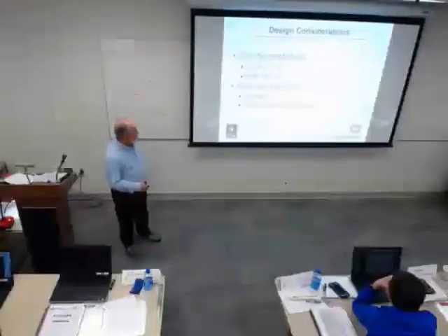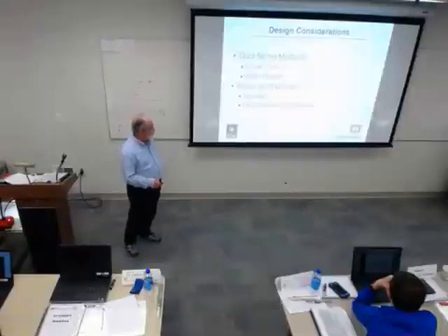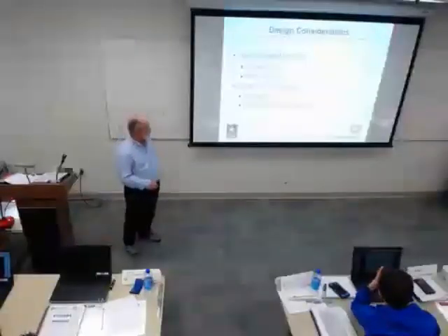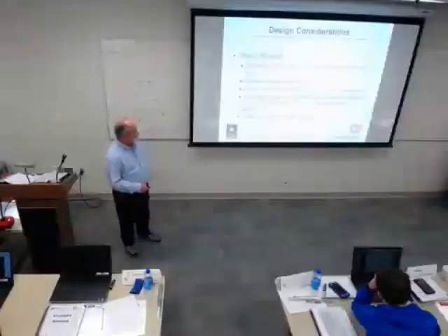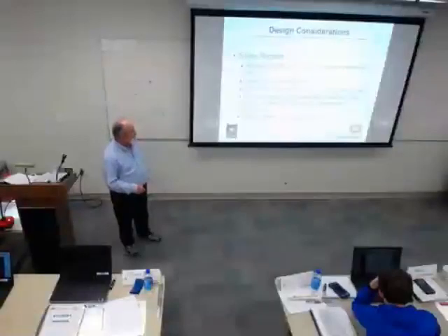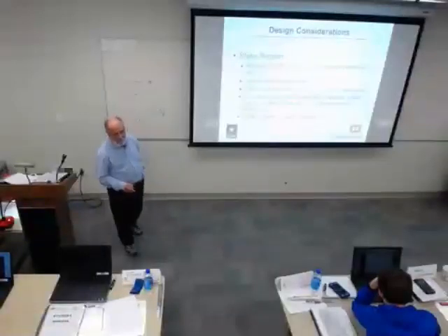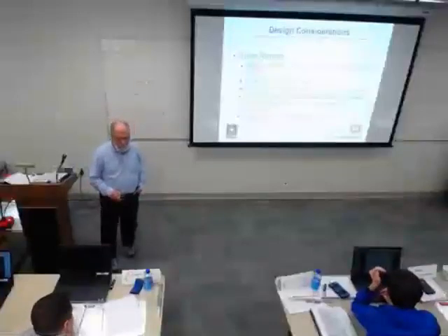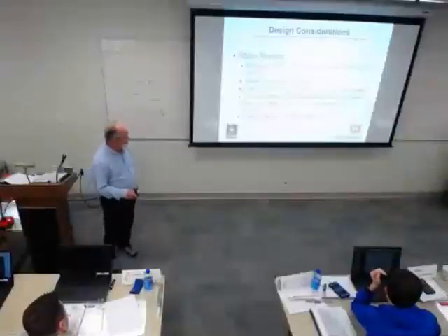And then we have the duct sizing methods: equal friction, static regain, and room air distribution with the devices and the expectations we have. Static regain is required, and the ultimate is an economic study. I haven't had time to do any real digging on it, but my experience as a designer is that when you're finished with static regain, you haven't gained anything.